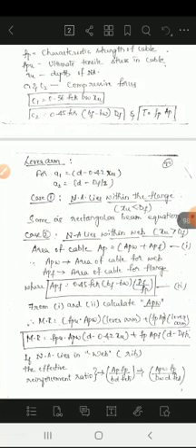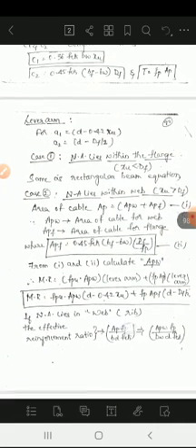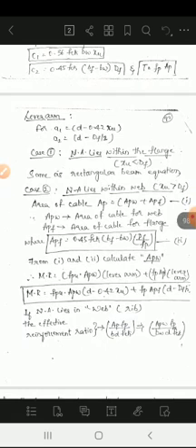So next, the moment of resistance formula will change. MR is equal to FPU into APW into lever arm, plus FP into APF into lever arm. So MR is equal to FPU into APW into (D minus 0.42 XU) plus FP into APF into (D minus DF by 2). The lever arm is, for the first case, D minus 0.42 XU. The second case, D minus DF by 2. This is if the neutral axis lies in the web.